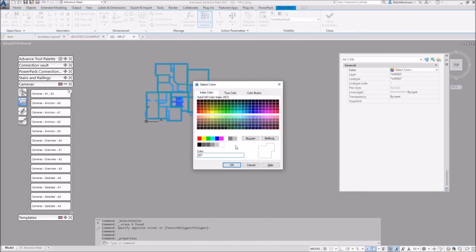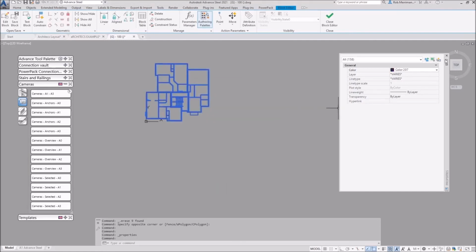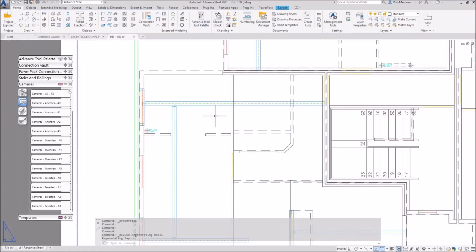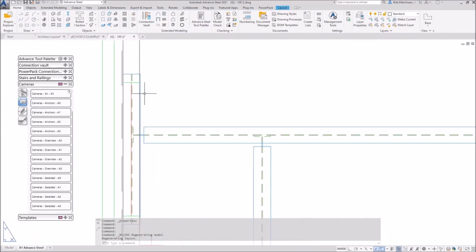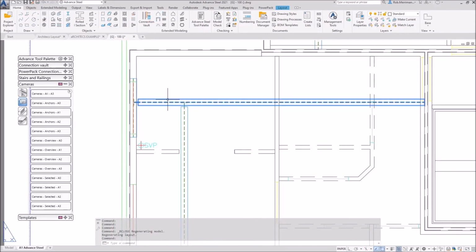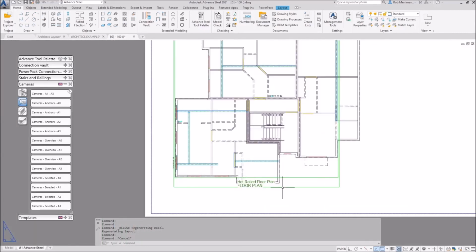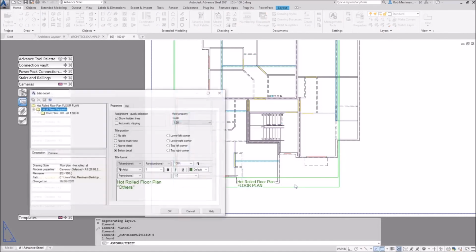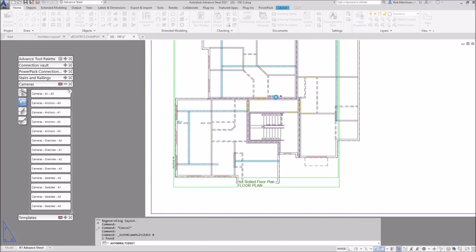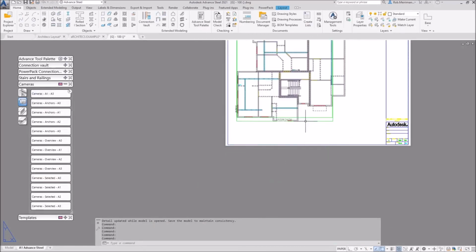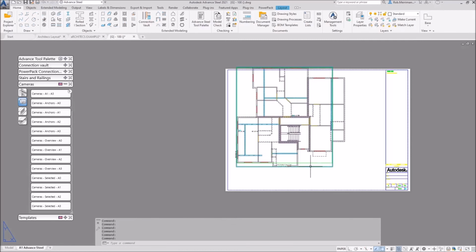Again, I like the 207 because it's what I used to use, and we used to make the outline faint, but then you can still see our steelwork in here with that architect's layout. And if we change the scale, that block will scale with it. So again, we move this and everything moves at the same time for us.